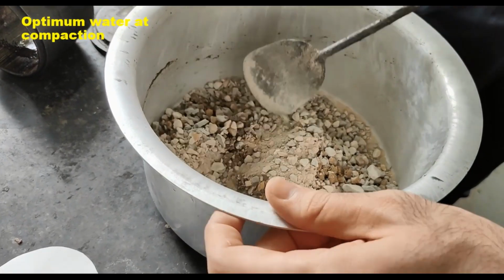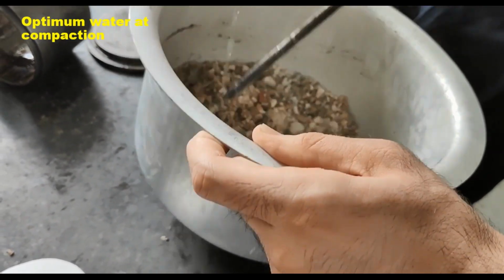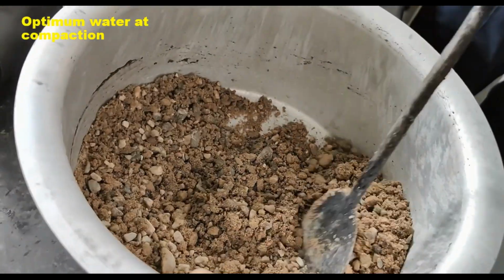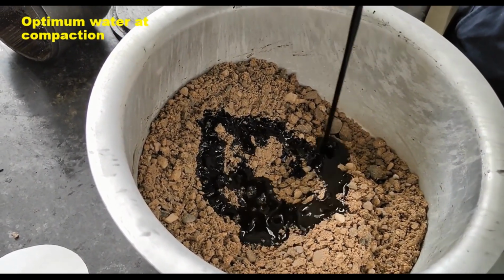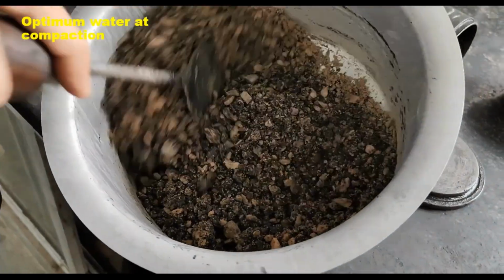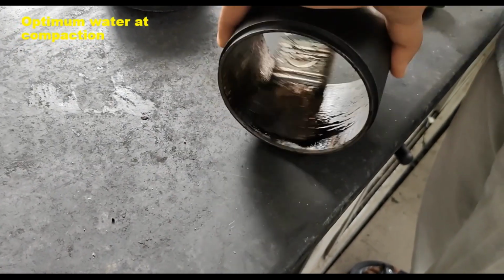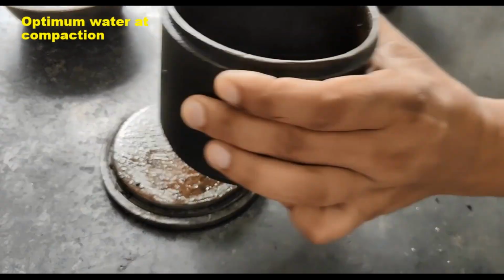Add water to it and mix it properly. If the water content is kept at 3%, then 36 gram of water is to be added, and the temperature of water should also be around 22.2 degrees centigrade. After that, add bitumen emulsion as we have done in the case of the coating test. For 7% bitumen emulsion, take 84 gram of emulsion, add it slowly and mix it properly, and here also 1 minute mixing is sufficient.